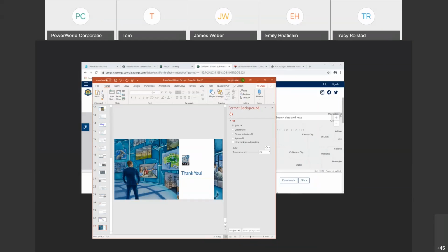And then we also posted some links to information on using the multiple element TLR, which we found has been a really useful tool if you're trying to screen locations. Early on, as Tracy was mentioning, you can look at GIS tools and other things to identify locations. On the electrical side within Simulator, you can run multi-element TLR, and that's really handy. We've done that with some studies where we just put in a bunch of contingencies. You first run the contingency analysis, and then you'll have a bunch of overloads come out of that. Then you can run the multi-element TLR on the contingency overloaded elements, and what you get out of that is a measure of which locations tend to relieve the overloading that came from that set of contingencies.